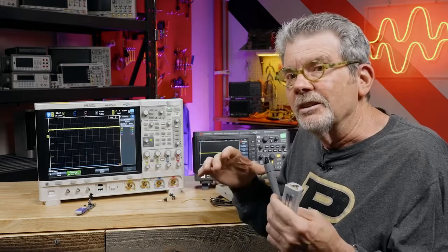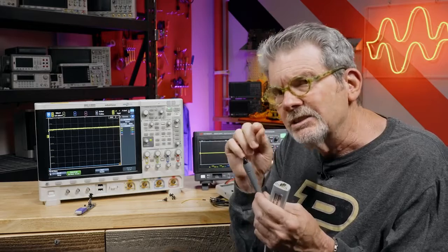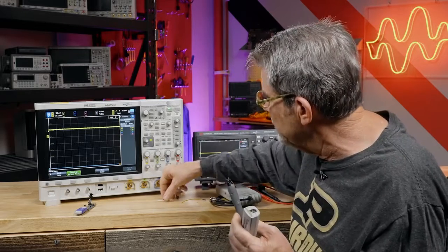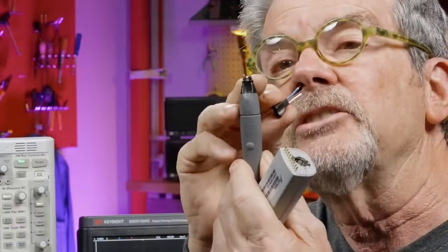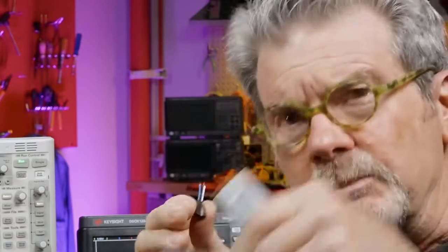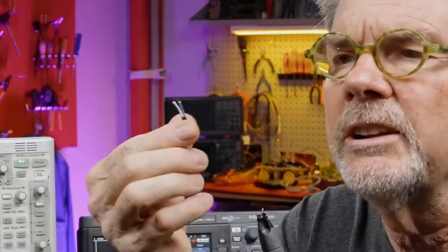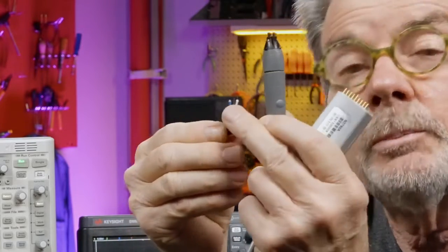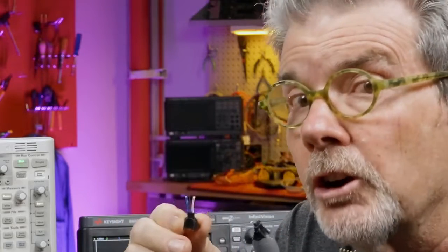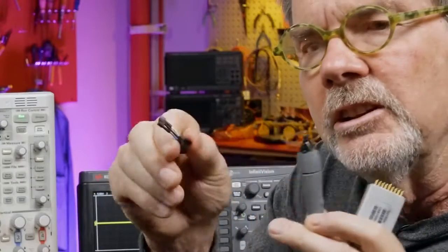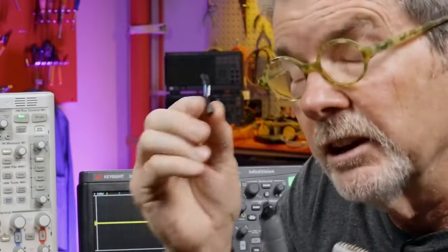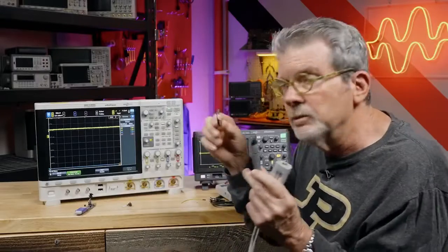Now, oscilloscope vendors typically provide some accessories to help you with the usability. Here's a couple of them I have here. This is a tip that I can replace, and you probably can't see it, two very short tips. Very difficult to probe. You can replace it with this tip that has a couple of short wires coming out that you can solder onto the board, then you can take your hands off. And this one here has sockets, so you can plug it into a header connector, and that's what I'm going to use in just a minute.